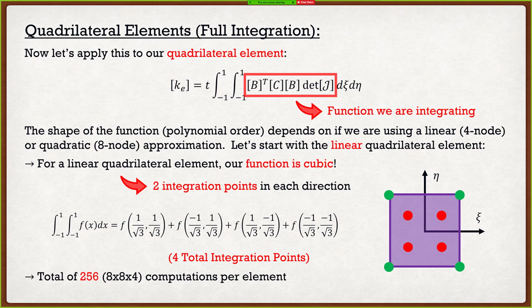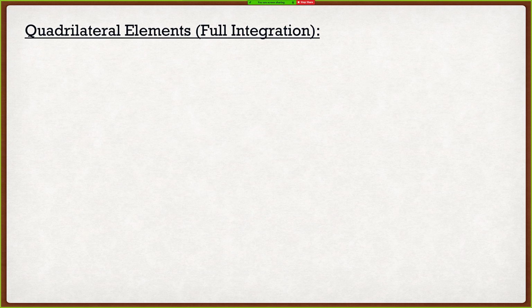What we're going to do is we're going to find our stiffness matrix C, and we're going to compare it if it's a square or rectangular element, and we're going to find out that it's going to be exactly the same as the integration. But if we provide a distorted element, then it will actually be an approximation. But the approximation is pretty good. So that was our 4-node element.